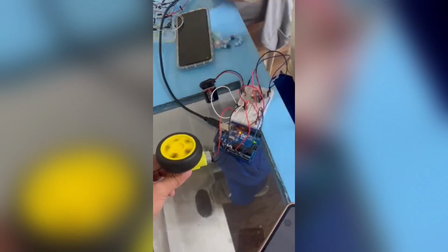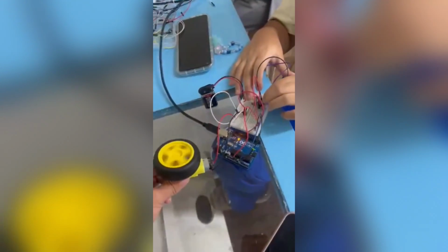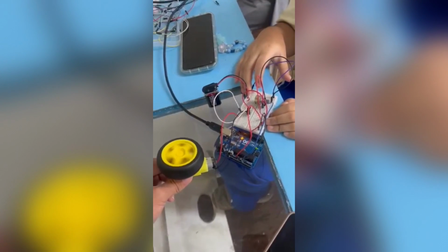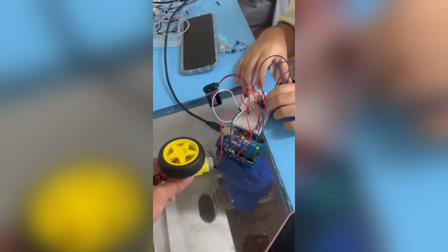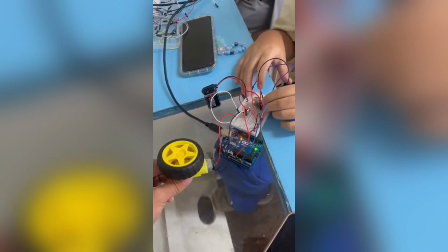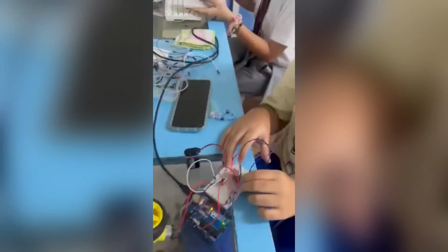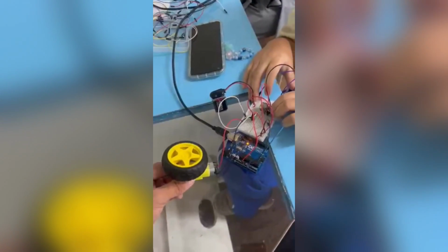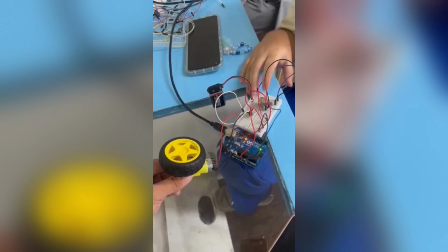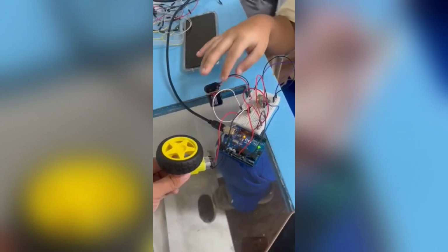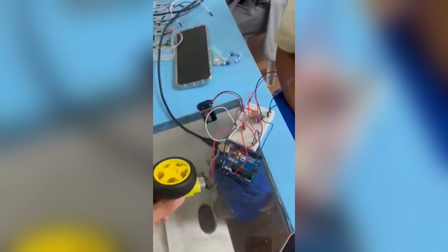This activity enhances the former one by adding a potentiometer to control motor speed instead of just turning it on or off. The Arduino reads the analog voltage from the potentiometer and uses pulse width modulation to vary how much power the motor receives through the MOSFET. Rotating the potentiometer changes the motor speed smoothly from slow to fast.